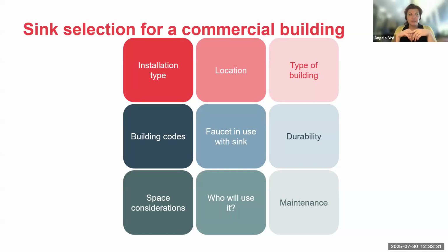The stainless steel is designed with the 316 stainless, so it's super corrosion resistant and it's a lot lighter to install. And it won't chip. 16 gauge stainless is really hard to dent too. Depending on the application, it just depends on what you would want to spec.